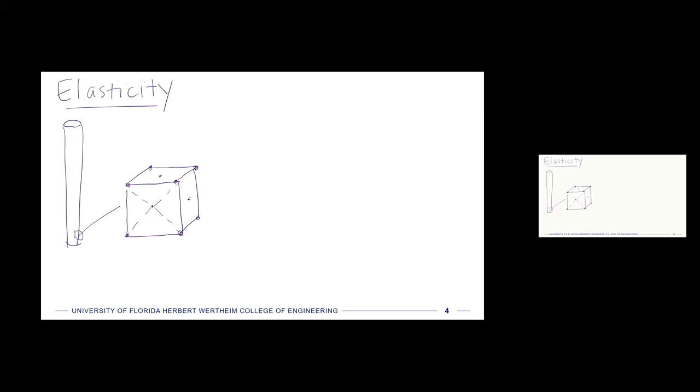We can think of all of these, if you want to, as a giant truss, right? So they're all together at the microscale. There's millions and millions of them. And so if we push on the whole bar or pull on the whole bar, each of these little units is going to stretch or contract correspondingly. And that's where elasticity comes from.